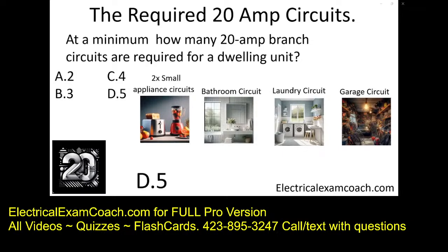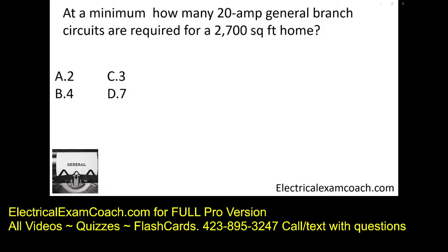Great job. At a minimum, how many 20 amp general branch circuits are required for a 2,700 square foot home? Now, your question may not say general. It may say for lighting and receptacles. You can keep an eye out for that. But usually if they give you the square feet, that's going to be the red flag for me that I'm calculating the general branch circuits.